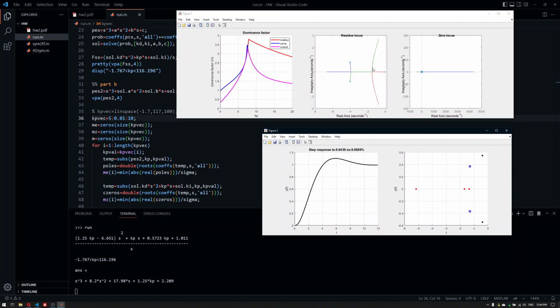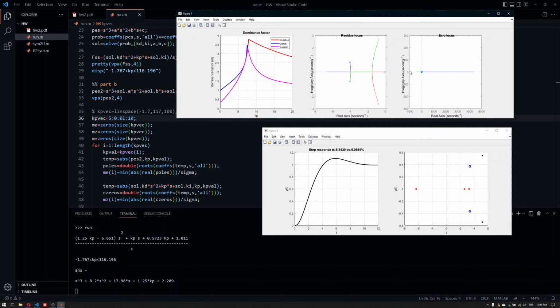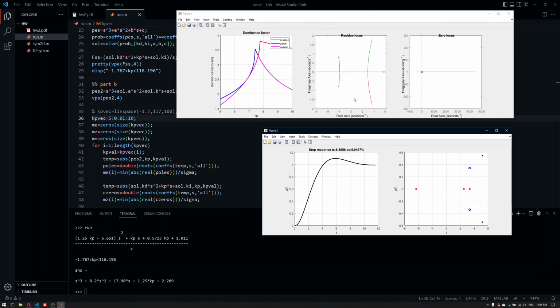Since we're using the root locus here, based on the root locus, we can end up in a fine interval, because this point is the furthest away. Here we are not seeing it anymore, but it was somewhere here, the conjunction. That was the furthest for the zeros. So use these two values, look numerically, and get the result that you are looking for. And you can see they are kind of aligned here. One of the poles is aligned with the real value of the zeros here, and it makes sense because that's the margin that we hit at that point.